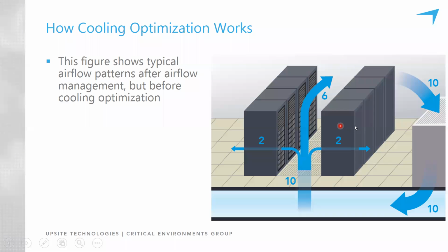So you actually can have bypass airflow flowing through IT equipment. Essentially just more air flowing through the IT equipment than is needed. This doesn't create any particular problems, but it is still wasting fan energy, moving extra air around that isn't needed. It's also reducing the return air temperatures to the cooling units, compromising the efficiency, and we'll talk more about that process in a moment.